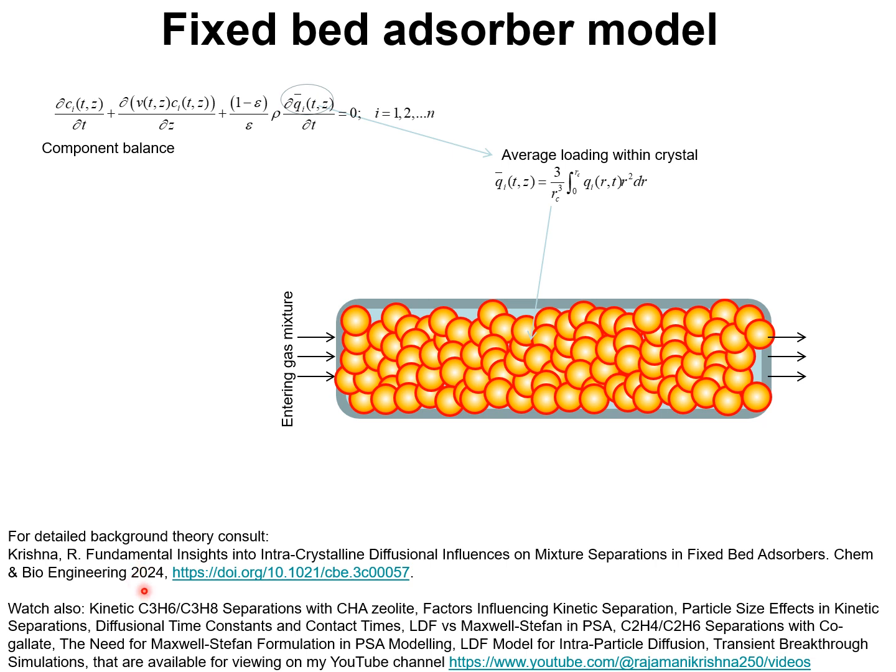As detailed in my 2024 paper cited here, and also several video presentations on my YouTube channel that are listed here, the modeling of a fixed bed adsorber for carrying out kinetic separations requires the solution of partial differential equations for each of the components, and this is the differential equation where C sub i is the molar concentration of gas component i at any time t and position z.